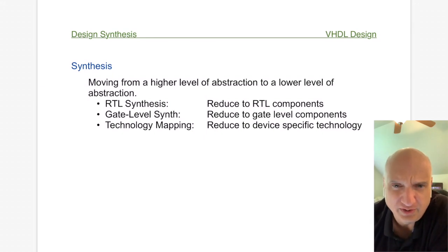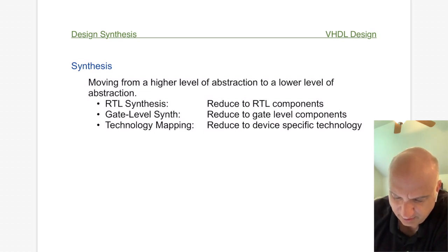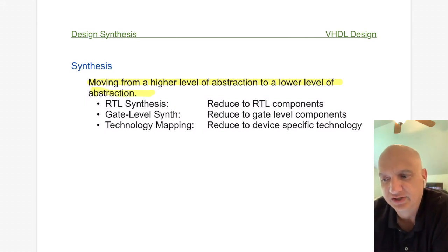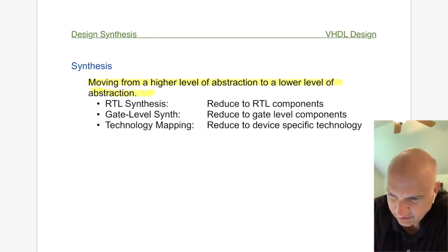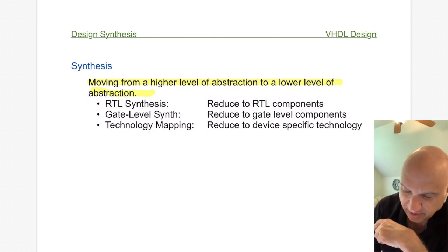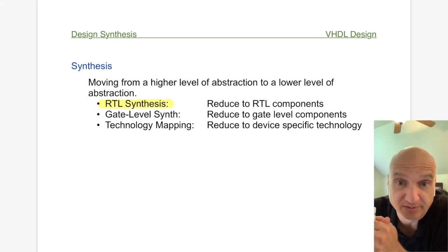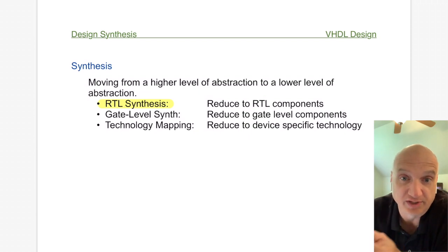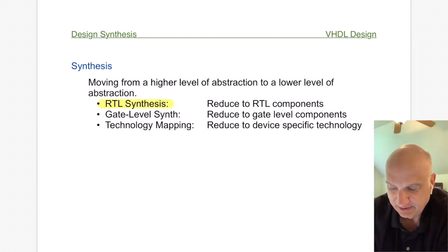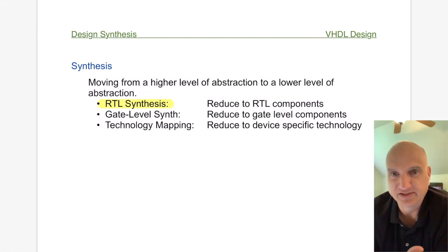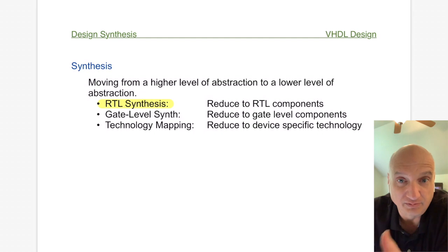Before we get there, though, let's talk a little bit about synthesis and the technical definition of synthesis. If we look at synthesis at its core, it's basically moving from a higher level of abstraction to a lower level of abstraction. The word synthesis means you take this high-level abstraction and then move down to a more detailed level, okay? A good example of this is RTL synthesis, which is very common in most of these development systems which synthesize VHDL code, right? RTL stands for register transfer level, and it organizes things in blocks, register-type blocks for storage.